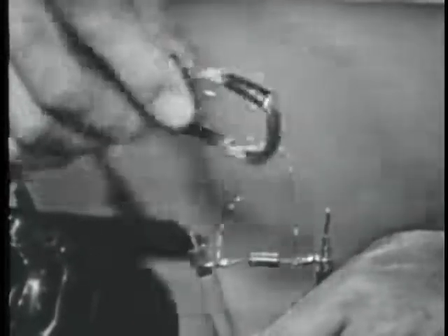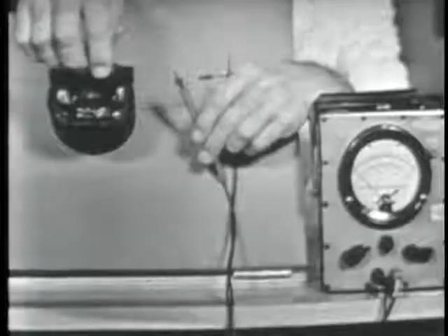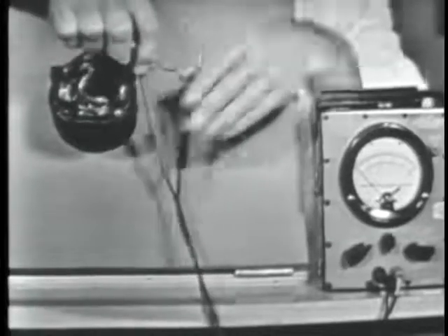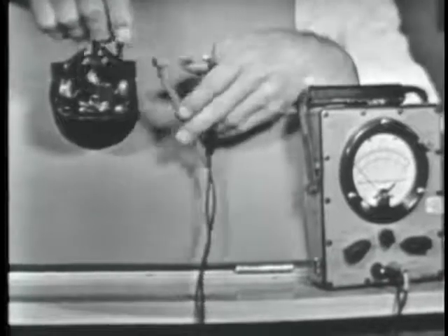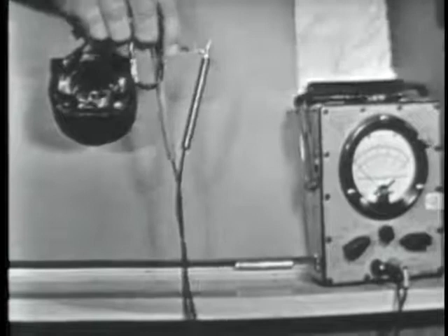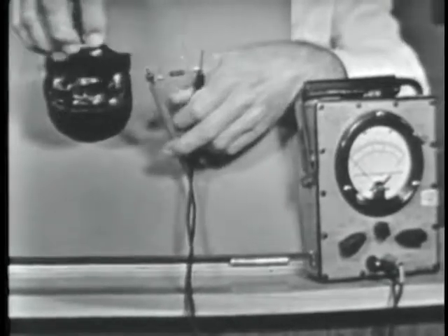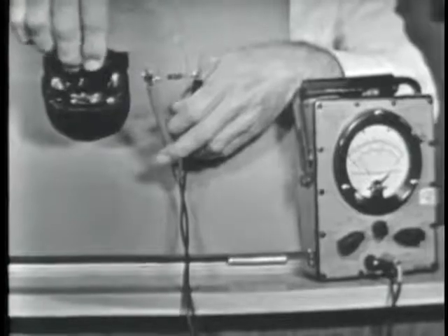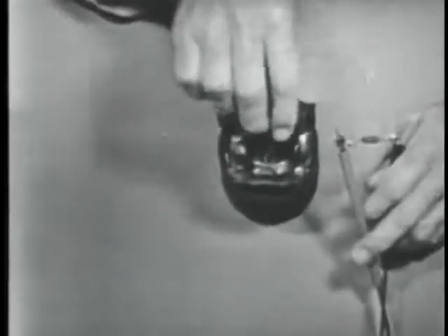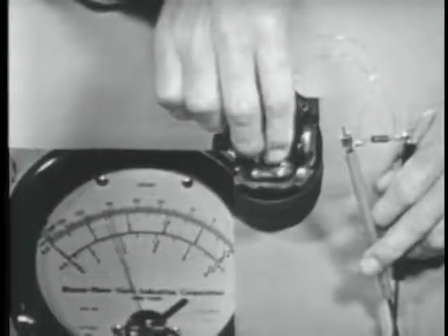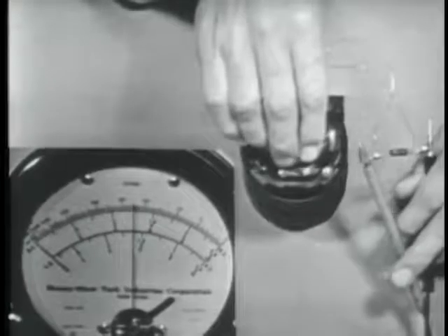Okay. All right, now I'm going to take the loop of wire and place it in the field windings. Now I want you to watch the meter on the PSM6 here. Now, let me apply the juice first. You may hear a little hum being picked up by the microphone because of this magnetic field. Now, as I place this loop of wire into the field windings, like this, you'll see, you've got something there. There, see, the PSM6 is indicating a voltage value.